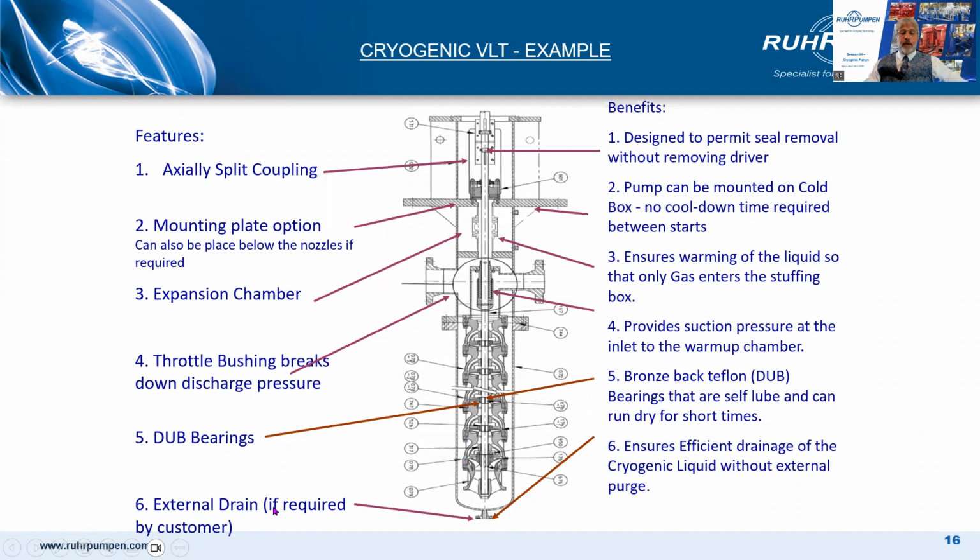Now, as we are pumping a clean fluid, liquid oxygen, liquid nitrogen, wear rings are integral rather than replaceable. There would be a risk of them loosening during warm-up and cool-down if we were to have removable wear rings. So we avoid that and use integral wear rings.